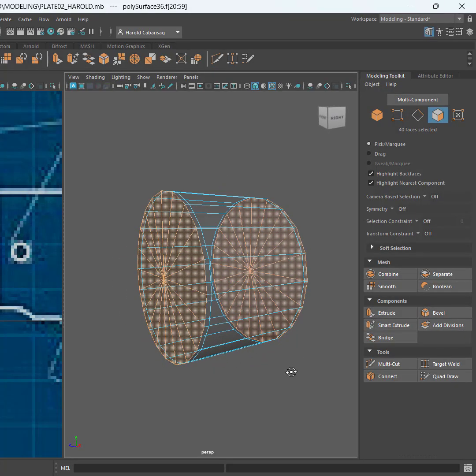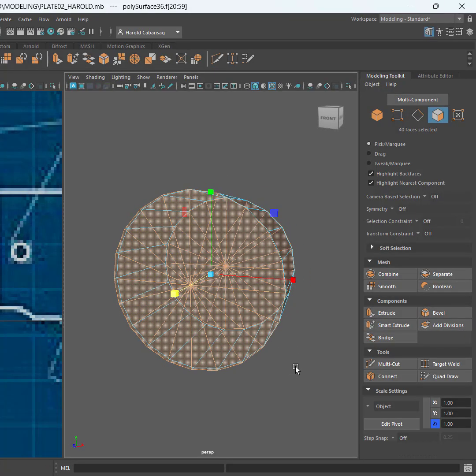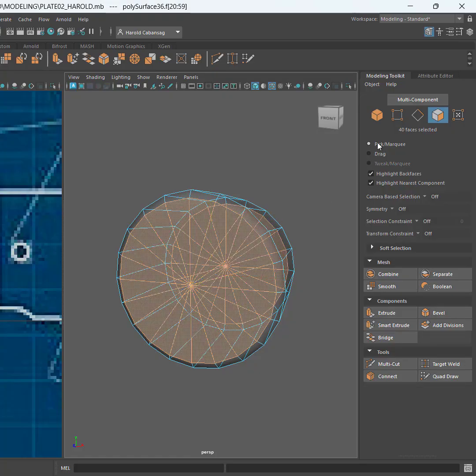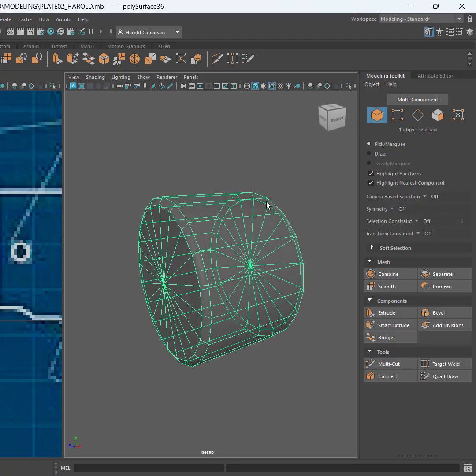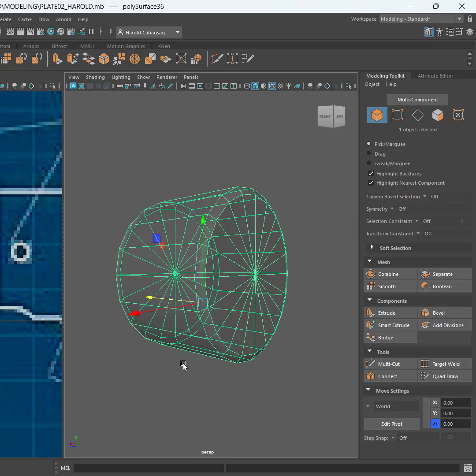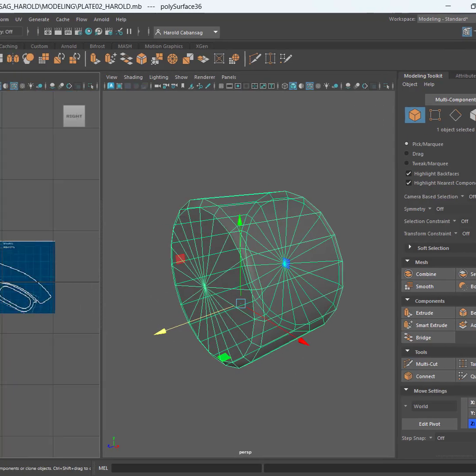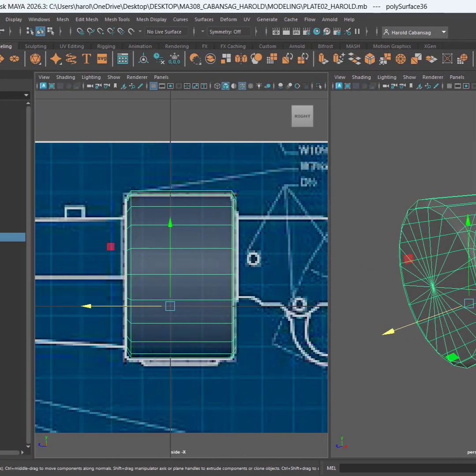And then I'll press R, scale again on this intersection here so that I can resize it and create that angle at the corners. There. And then I'll press Q. Then I'll switch to the move tool, W for move, there it is. So now I have followed that detail.